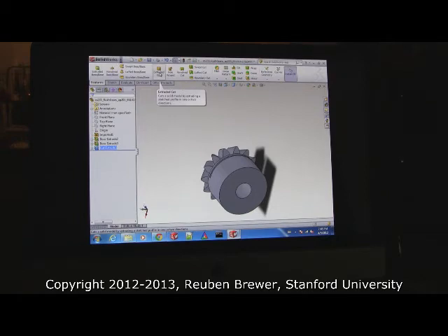So I don't know why, and it does this to me all the time, where you did everything nominally right, and it just refuses to do the feature. I think it's because they have monkeys programming at SolidWorks. It's just non-deterministic bugs, which are my favorite type to debug. So. Okay, so it's at 1 inch, and you press the green check mark. Yep, and now you've got a cut. No, it says the sketch is both open and closed. Oh god. Is your center line dot dash? Yes.